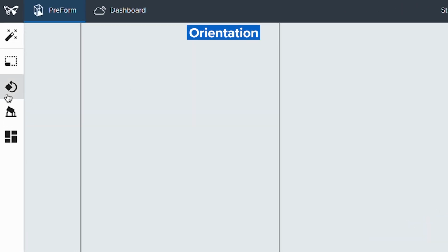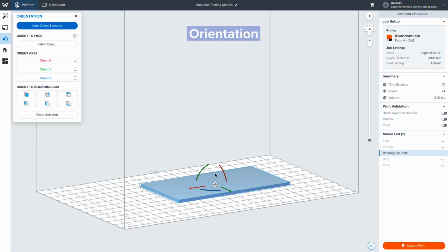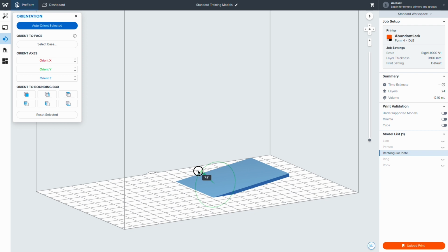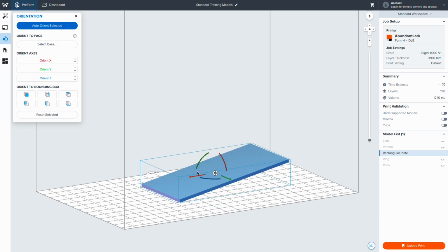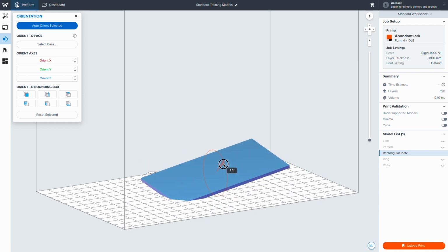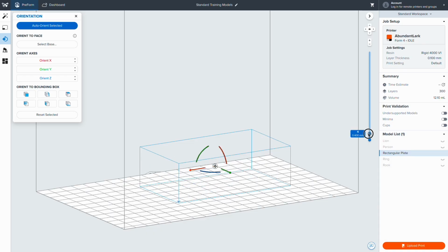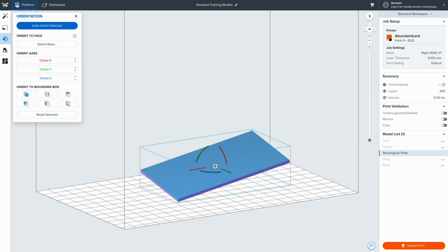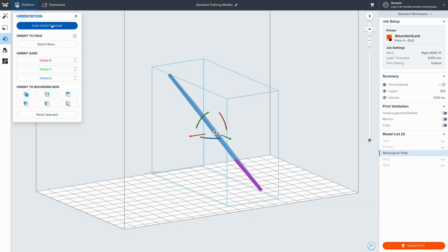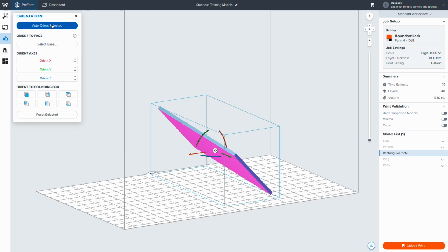As for orientation, Formlabs recommends applying a 10 to 20 degree angle on your parts in 2 axes. This is for best outcomes when printing with supports in SLA printing. This allows for a gradual increase in the amount of surface area each layer has, ensuring an ample foundation for subsequent layers to form. There are a few ways to use the orientation option to orient your model in PreForm. The Auto Orient feature will provide recommended orientations for your model.